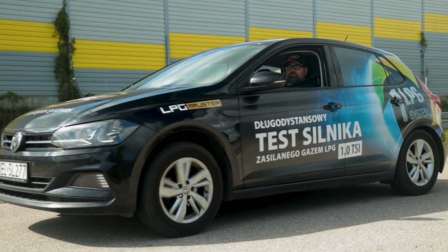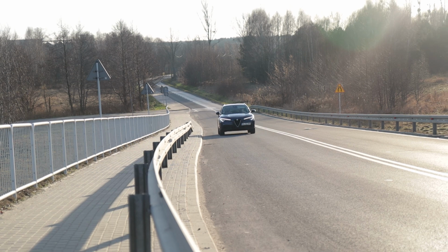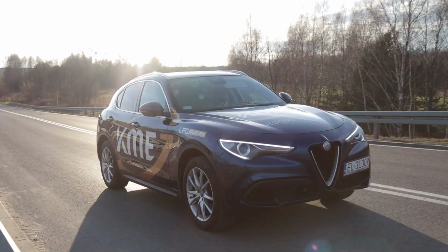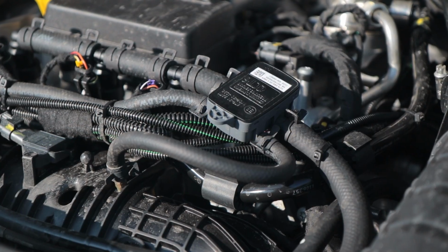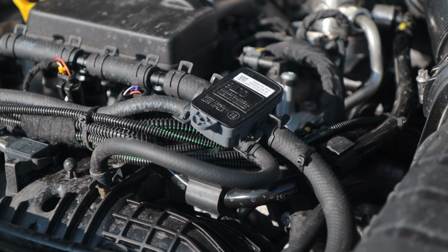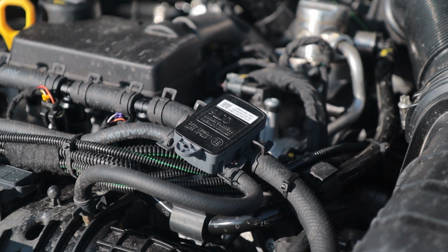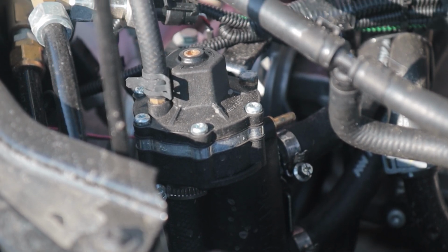We recommend using this sensor for cars with a boost of more than 1 bar, that is, above 2 bar of absolute pressure in the intake manifold. Installation of the CCT6 analog 5.5 bar sensor is also recommended when using a variable pressure reducer, adaptive, e.g., Mustang 8S, whose output pressure increases with the pressure in the intake manifold.